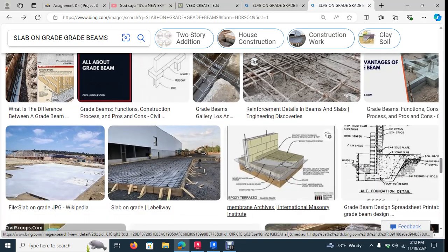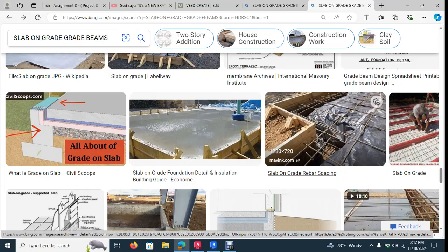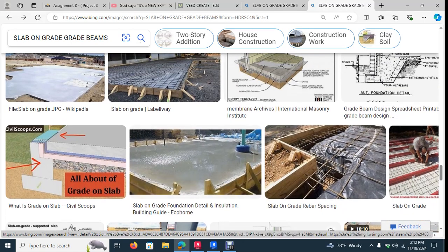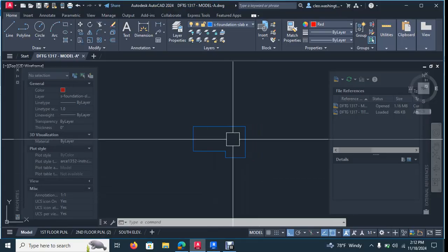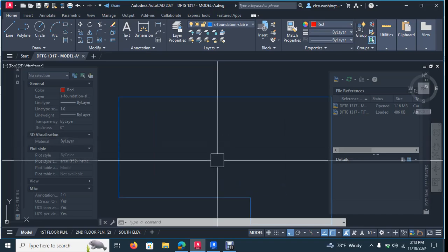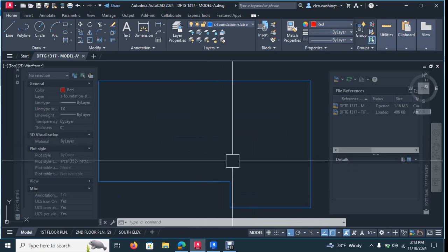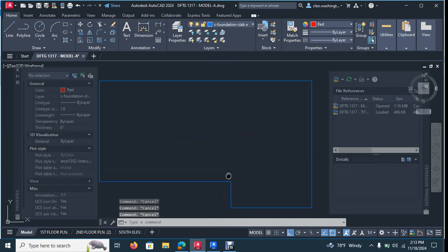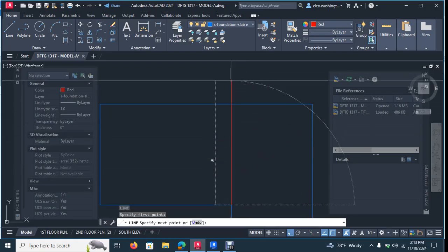Okay, it's really a good experience to actually go and see this while they're pouring the concrete. But at any rate, if you're not in the industry, that's something that you probably won't see. Now, typically grade beams run the shortest distance, okay? And typically they're like 4 feet apart. So let's say if we had a grade beam here, and I'm gonna draw them in red, and we'll come back and we'll apply, okay?